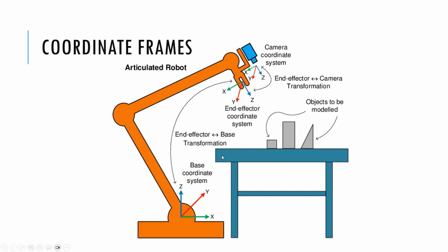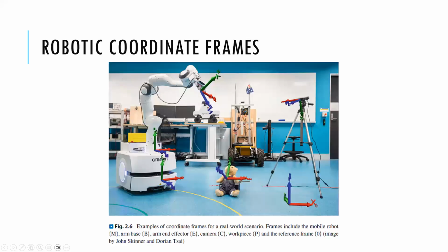If it's a 6 degree of freedom robot, there are 6 joint variables to actually make the robot move. Then the end effector will be equal to the object position, and for grasping, you just have to close the gripper. So we're going to talk about that motion, which is the kinematics today, and that's really the goal of today's lecture.